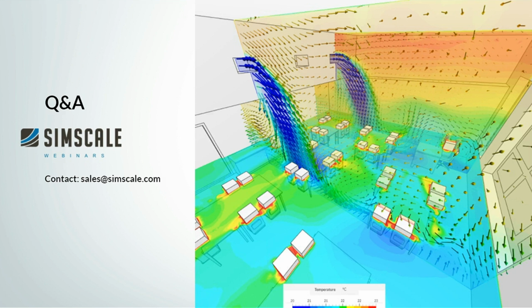Thanks, Richard. So let me take the next question. It's an interesting question. Natural ventilation amount can be affected by the amount of wind and its direction. So for this particular model, what we did is we took the external wind conditions, and obviously we took an average value of the wind that could actually enter the windows and supplied that as an input for the internal case study. So that's the approach we took to make sure we are considering the change in wind direction and changing wind conditions on the external side.